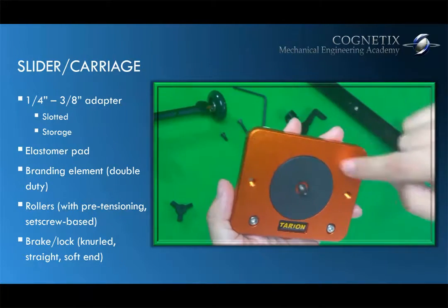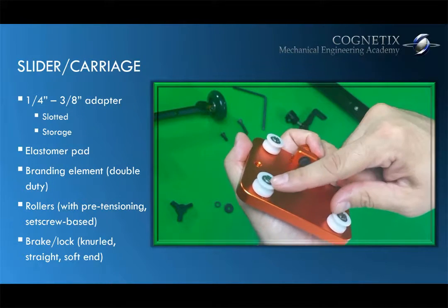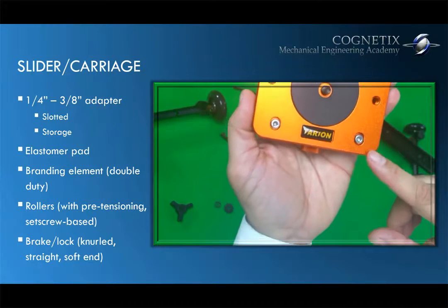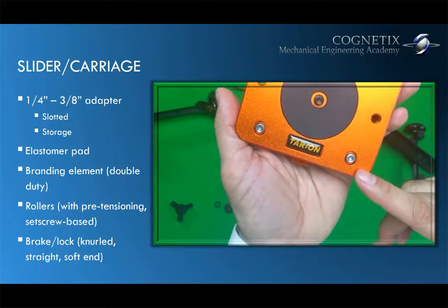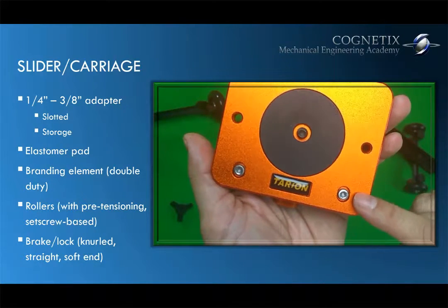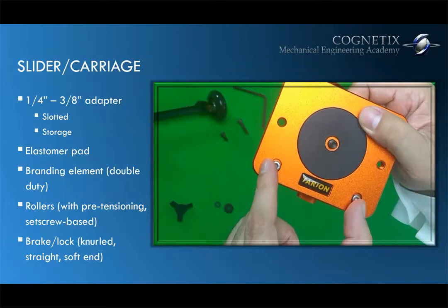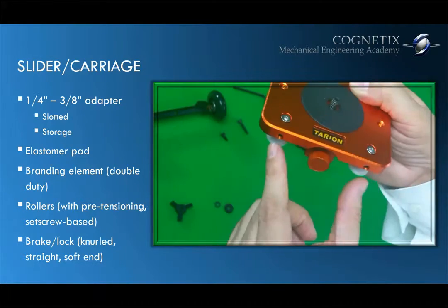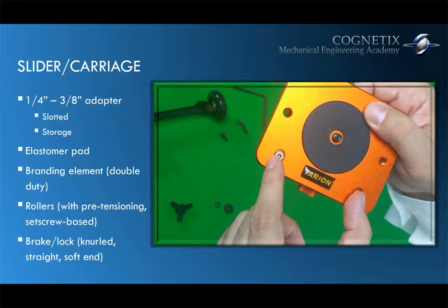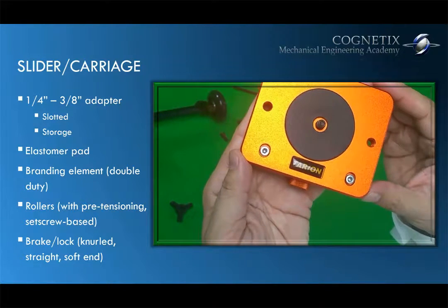The 2 rollers that are up here, these guys, have a fixed axis. The axis does not move. However, the rollers on the other side, you can tell, let me zoom in a little bit closer, it's a slotted hole. Okay? That tells me that these 2 axes for the rollers below, we can move the axis closer to the rail and farther away from the rail. So it's an assembly process.